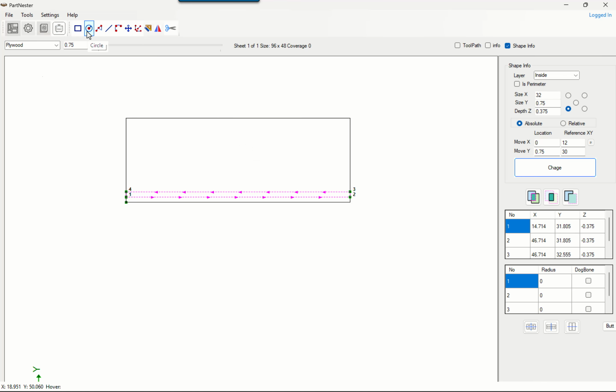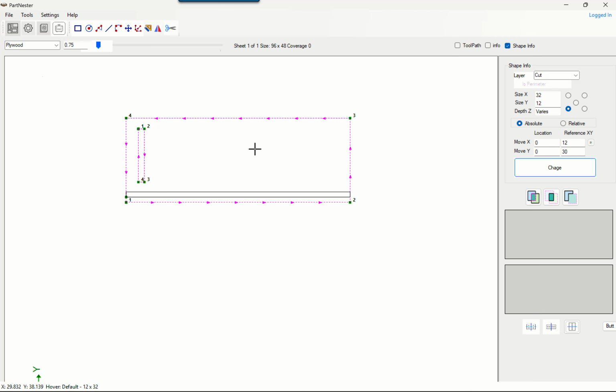We also have centering tools. So if I have another rectangle and I want to have that centered across the top, we'll hold the Shift key down to select the other object and hit the center function, and we see that that just shifted centered.